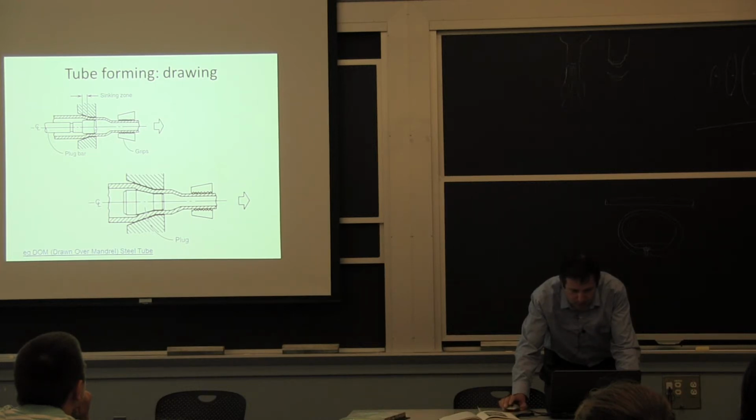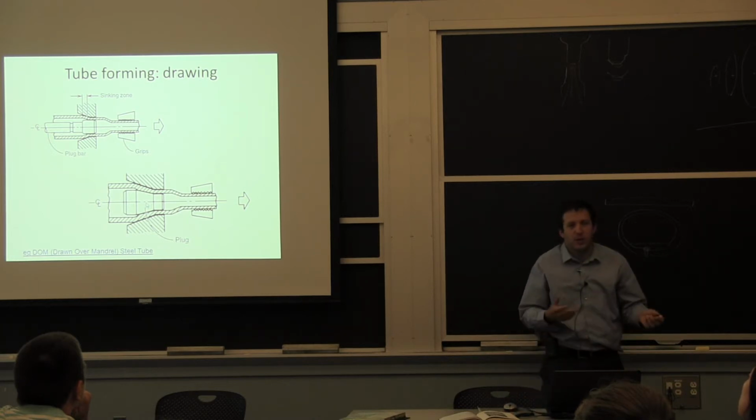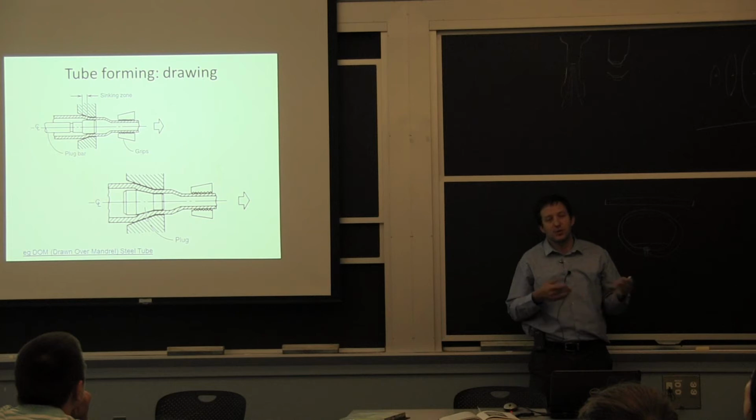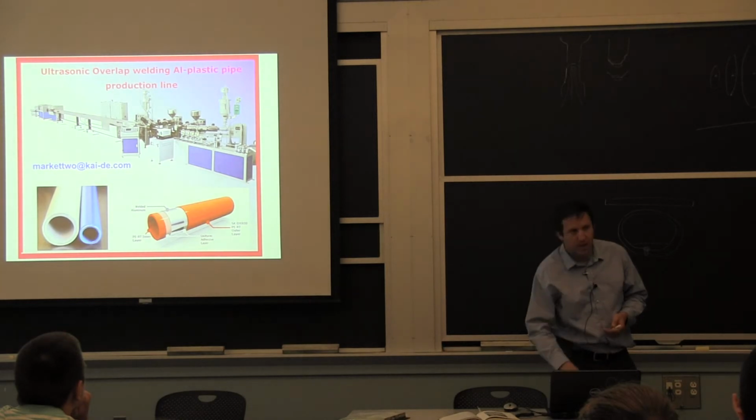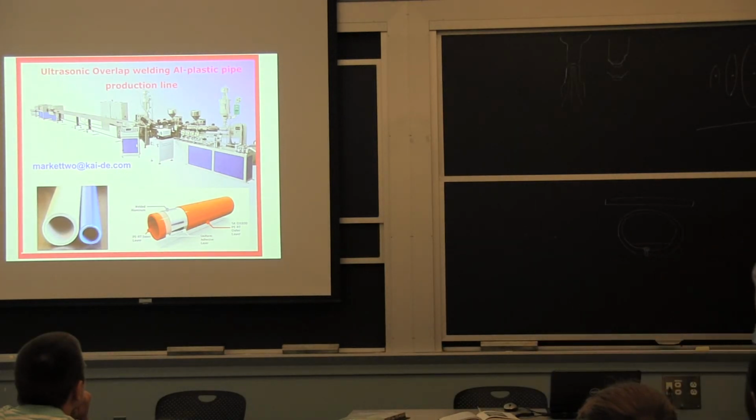And you have to control the speed. Here they have the internal mandrel or plug, they call it, for drawing is being hauled. Here it's just floating. So there are different ways to do it, but now you're not so much of a continuous process anymore. The previous image that I wanted to show you, and these are the handouts.